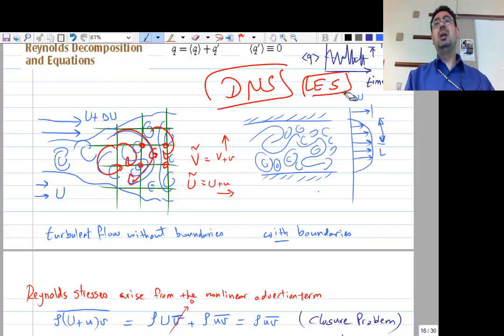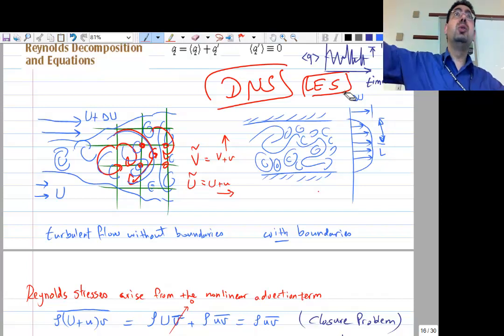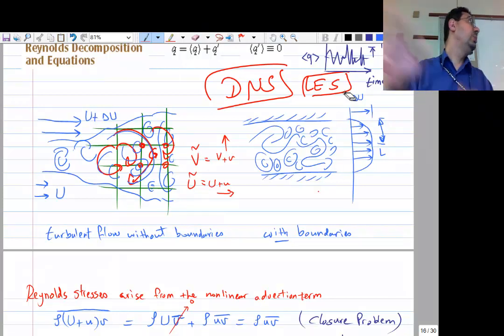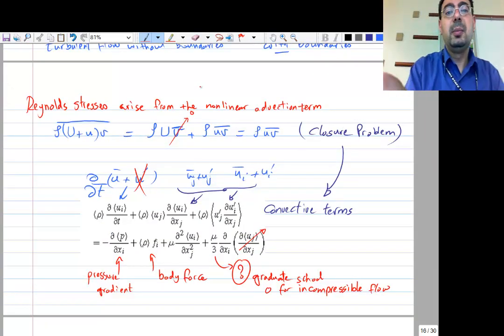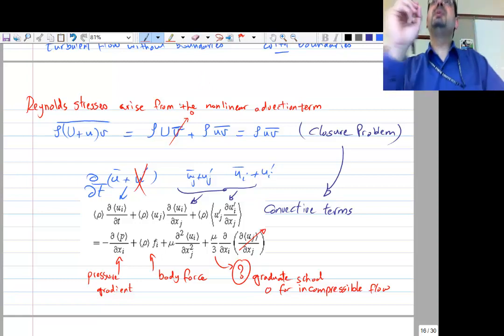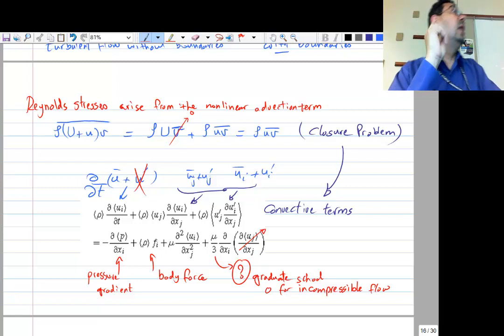So both of those are not really popular with industry. Once you graduate and work with companies, they don't want to do direct numerical simulation and go to the supercomputer, and they don't want to do large eddy simulation and run for weeks either. They want the run to be finished tomorrow. You come back tomorrow and tell them how quickly the air should move in that boiler, or how large the velocity should be inside the burner. So what they do is something called the K epsilon model, right? The K epsilon model is what's popular with industry. That's how they model turbulent flow.